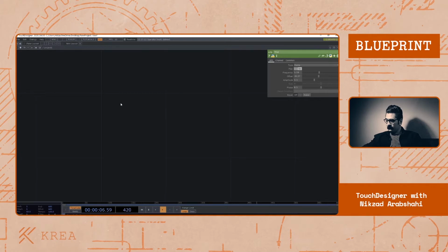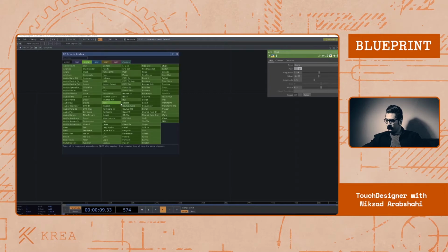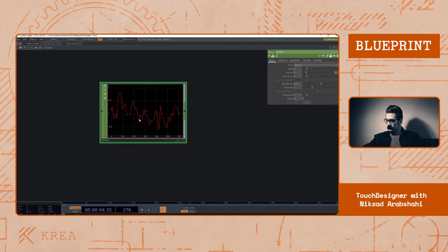The other useful chop for generating waves is noise chop. Noise chop generates a unique wave without repeating samples with a value range of -1 to 1. With the noise chop, you can generate waves or curves with different shapes. Again, same as LFO, you can adjust the period, change the amplitude, change the scale of output, change the harmonics, and more and more. I'm going to explain all.